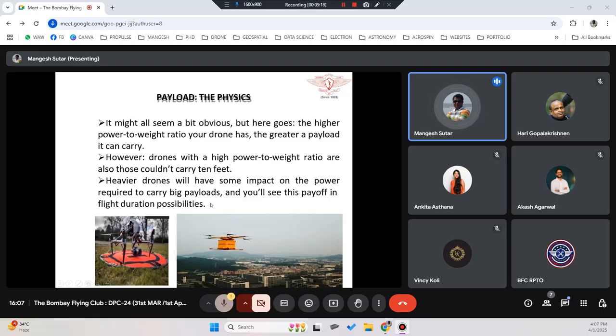Like I gave an example, my AgriBot drone is built for 50 kg of weight. But when I am attaching a payload, I am considering only 50% of its capacity. So I am putting a tank of 10 liters, which, when filled with the fertilizer, can weigh only up to 24.9 kg. So I am using within the limit. Assume that I remove that 10-liter tank and put a 16-liter tank, the weight of the drone increases from 24 to 28. So with my 10-liter tank, I am able to fly the drone for 20 minutes.